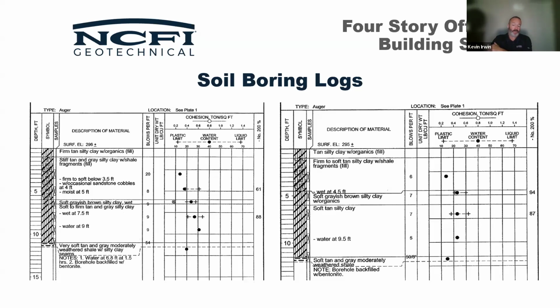In this particular case, we actually went out one weekend and worked at this location. This was when I had my contracting business. We lifted it, and everything looked great. When we came back the next week, it had settled again. After some head scratching, we found that we had gotten hydrostatic lift. We pressured up a bunch of water, and over the week that we were gone, that water pressure dissipated. When we came back and found that it had settled again, that's when we went back to that bottom-up approach.